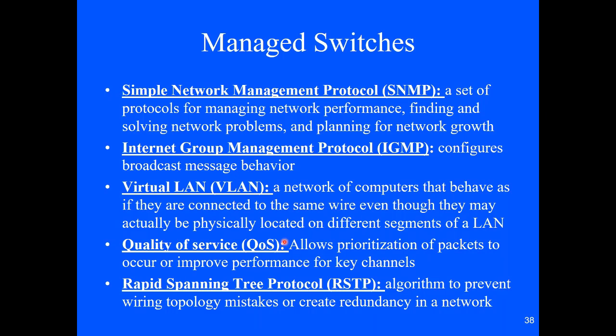QoS is quality of service. That's very, very important. In, say, a protective relay application, if I send a trip signal out, I need all those other devices to trip immediately. I don't want it to wait in its queue. I want it to be prioritized. So you can actually set prioritization levels from 1 to 8. So I can make it where that bypasses and immediately goes out.